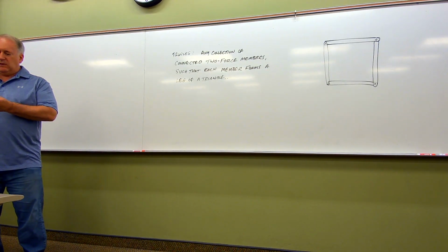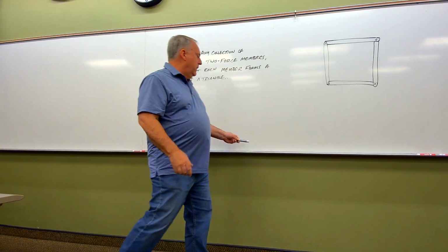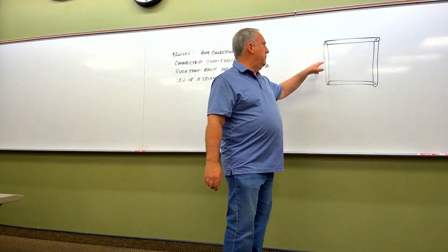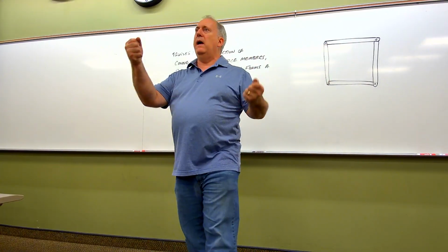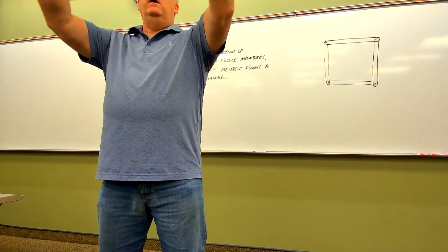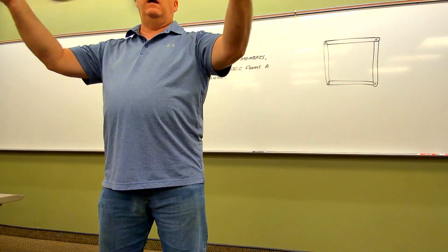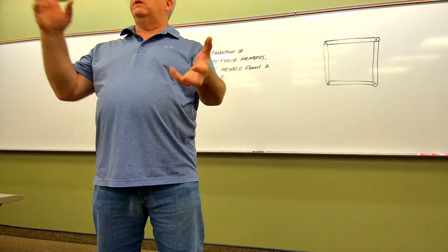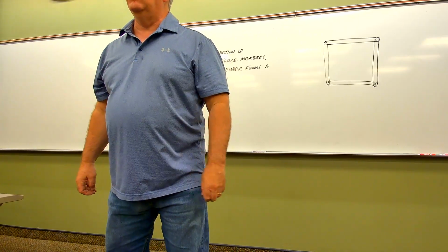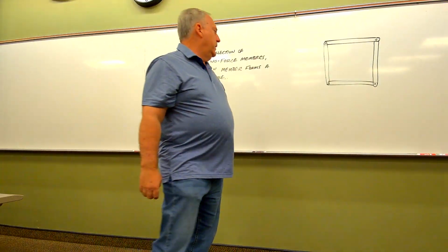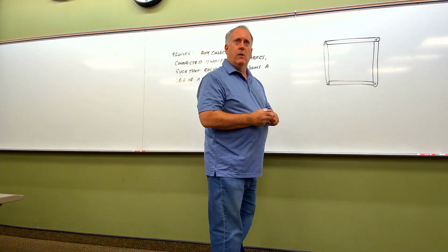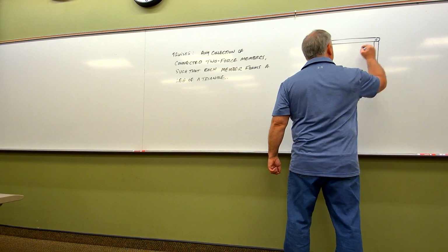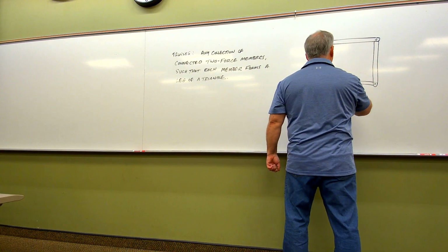No. And think about this, folks. If I really did have four two-force members like so right here, and I've got these things all connected up by merely pins, is there any way that I could actually hold that connected square, in this case, of two-force members and just kind of toss it out to you and assume that it's going to have the same shape when it lands on you? Nope, not at all. So what would make this a truss? Add one more two-force member. It can go diagonally here, it can go diagonally here. It doesn't make a bit of difference.